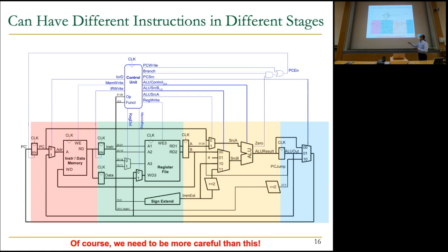So you need to do something else over here. This instruction, which instruction does it specify now? So you cannot really chop up the machine like this. You need to add more registers so that you know which instructions are being processed in different stages. So we're going to increase the hardware cost clearly compared to the multi-cycle machine. And that's going to be one of the shortcomings of pipeline. Does that make sense? At least the basic idea?